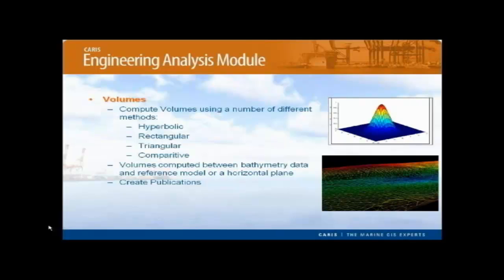Now, all of these volumes can be computed between the bathymetry data and a reference model, or the bathymetry data and an infinite horizontal plane for a more simple calculation. The results are stored as an XML file and can be exported to a text file or turned into a publication using the new publication tool in Bathy DataBASE.